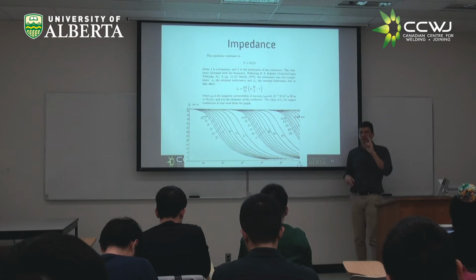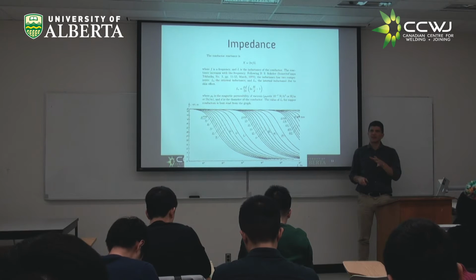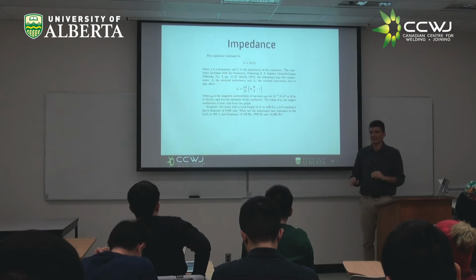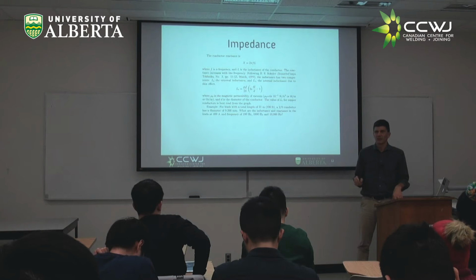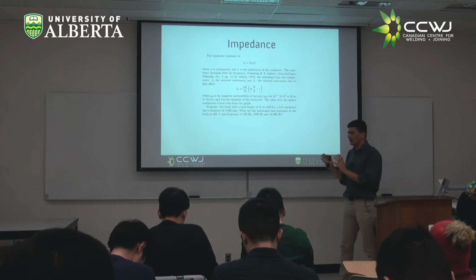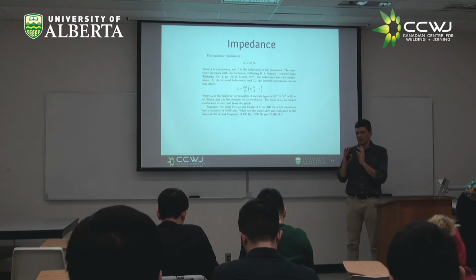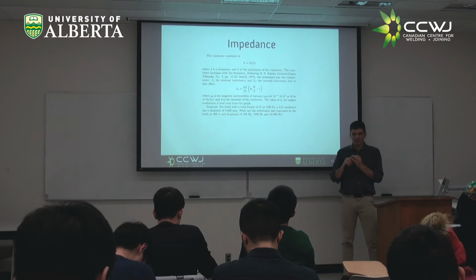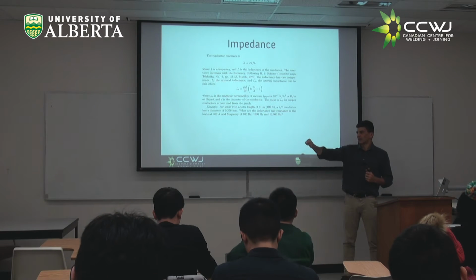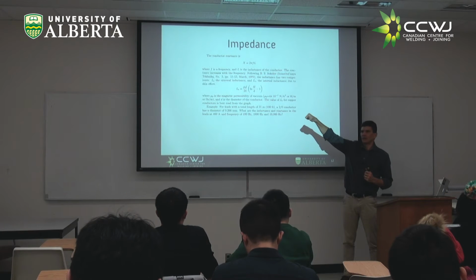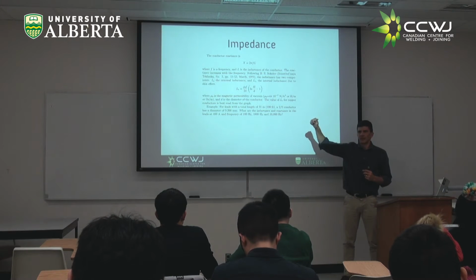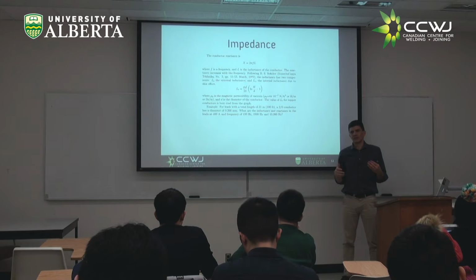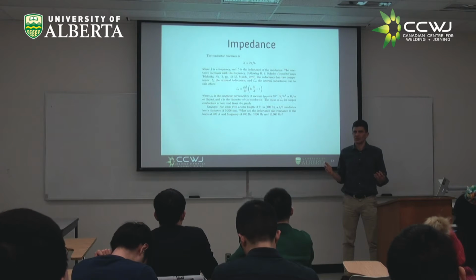Inductance has two components too. One is related to skin effect, which comes from this graph, and I know it's very small. So I'm going to do all of us a favor and skip the skin effect, right? But we still have the inductance from the length of the lead. And this is kind of funny. Remember, I mentioned a conductor generates a magnetic field according to this rule. If the current flows this way, we generate this magnetic field around it. So this magnetic field creates a very weak inductance, but it's not zero, and it matters.